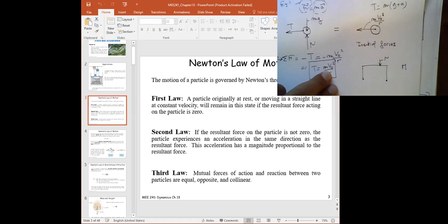At each support, there's a reaction. Bravo. So I'm going to have, let's call them, R1 and R2. Can we say also friction, doctor? There is friction if it was moving, but when it's not moving... Okay, and there's its weight. Where should I put the weight? At the center of gravity, in the middle somewhere. Exactly, bravo. So here, the CG doesn't actually have to be on the actual part, right? It would sometimes be in the air.